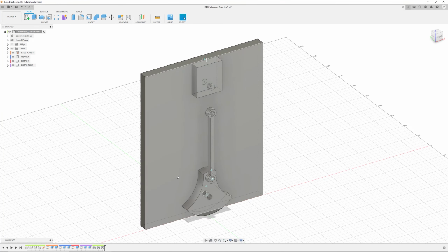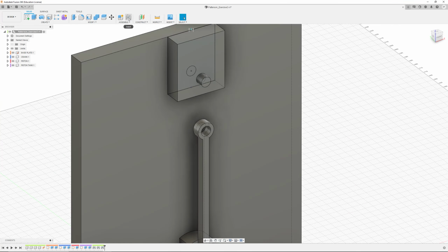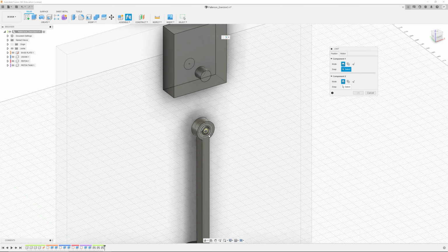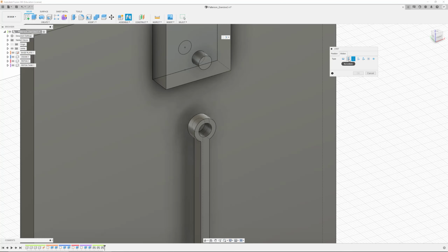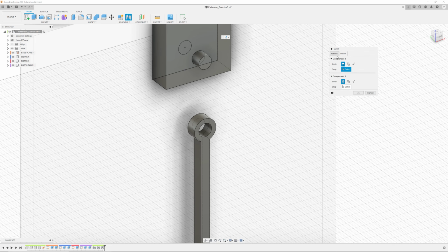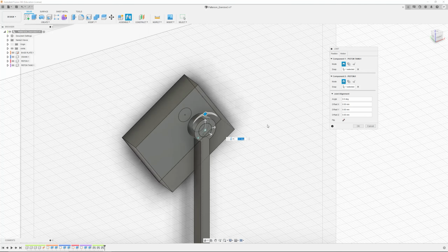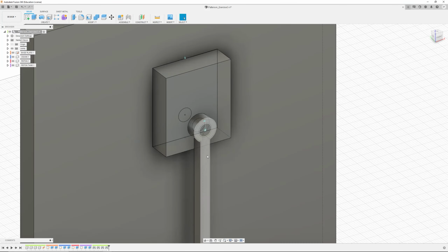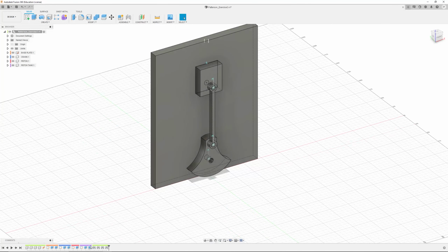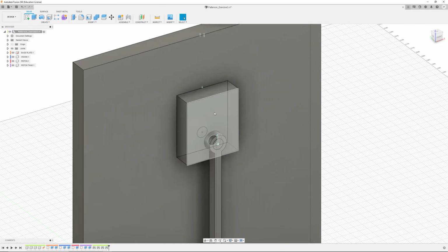And then the last thing I'm going to do is make a second joint. So the solution here was that I needed two joints in order to make this work. So then I'm going to use the revolute, select that, and select that, so that it's revoluting on that. And then I'll hit OK. Everything is all green down here, happy as a clam. And now this is locked into only moving vertically, up and down, which is what that first one was.